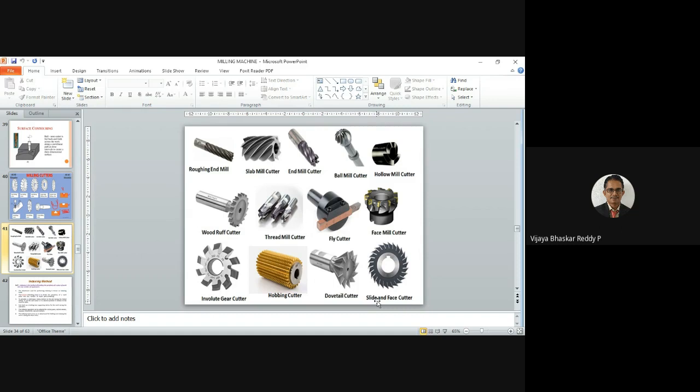To obtain the gear profiles on the circular disc, we are going to use an indexing methodology, which is attached to the milling machine. You can ask why the indexing methodology is attached, because here we are creating slots or spline generation, equal slots around the circumference of a round rod, and also gear profile cutting on the circular disc. We need equal arrangement of gear profiles, so we need to follow the indexing methodology.